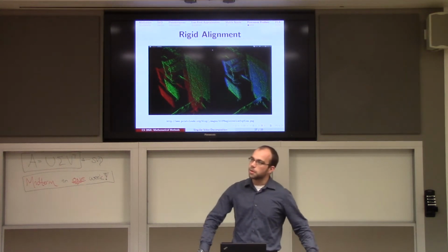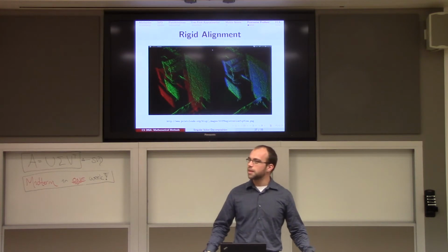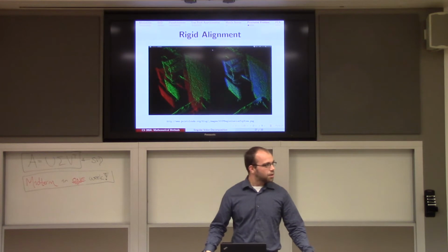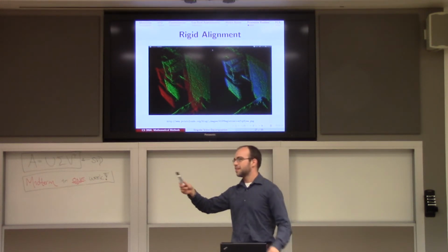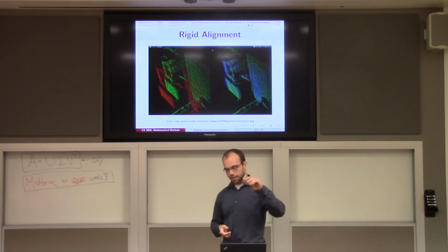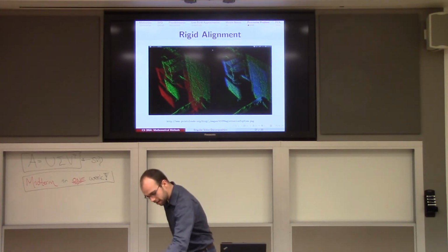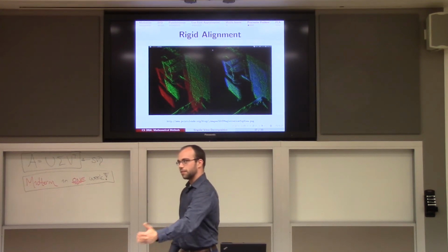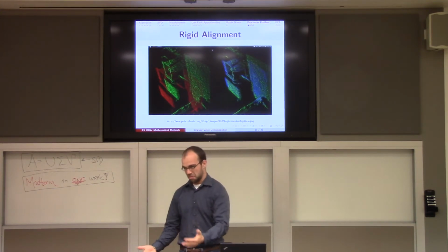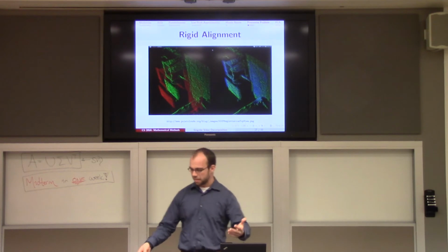So a big problem when you deal with this type of 3D input is something called registration. So let's say that I want to make a 3D model of this marker, right? Now if I sit him, never mind the marker is kind of small, if I sit him down in front of the Kinect and the Kinect is sitting here, I can only expect to get points on the front half of the marker because just like you and I, the Kinect can't see the back half.